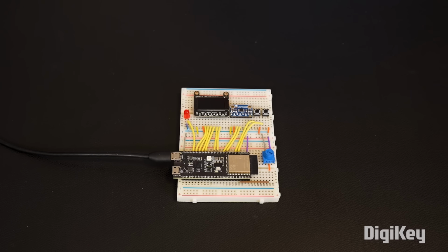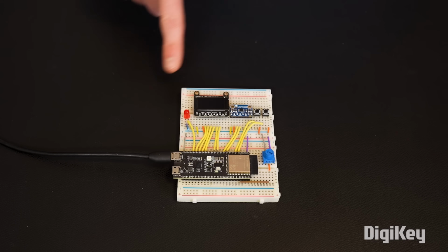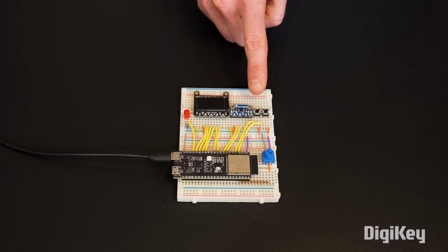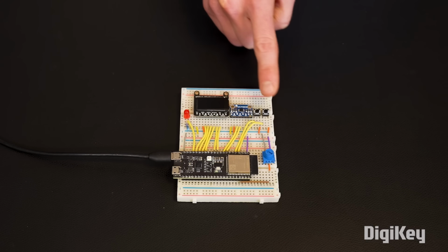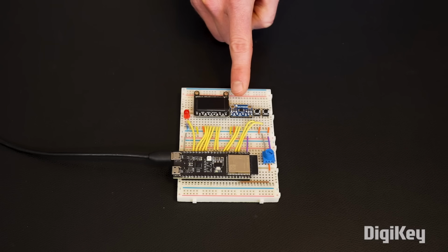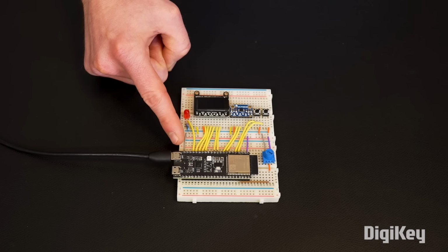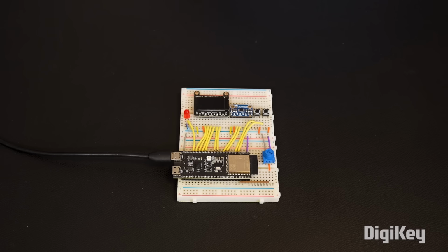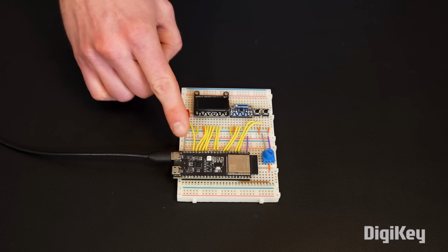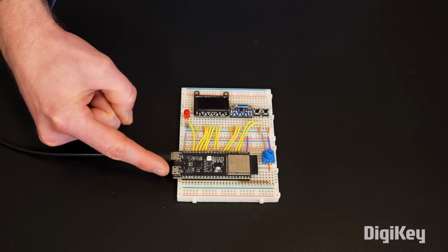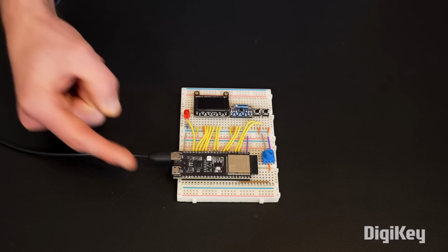If you'd like to follow along with this course, I highly recommend setting up a breadboard as I've shown here. You'll want to connect an LED, a couple of buttons, a 10K potentiometer, an MCP9808 temperature sensor, and a SPI LCD with an ST7735R driver chip to your ESP32S3 DevKit C board. You'll also want to make sure that you plug the USB cable into the UART port. We'll use the USB port in a later episode for debugging.